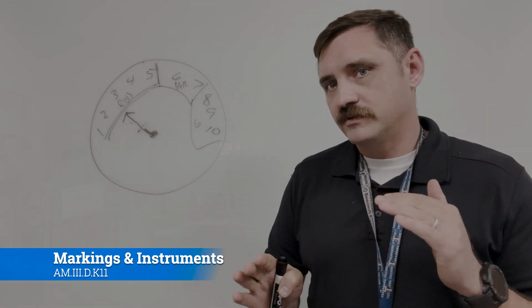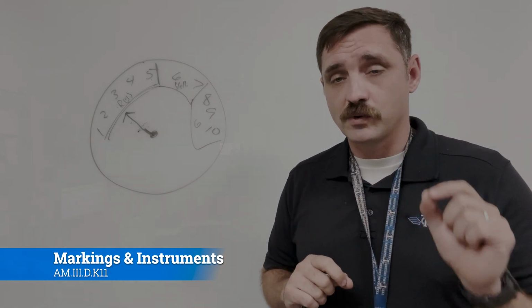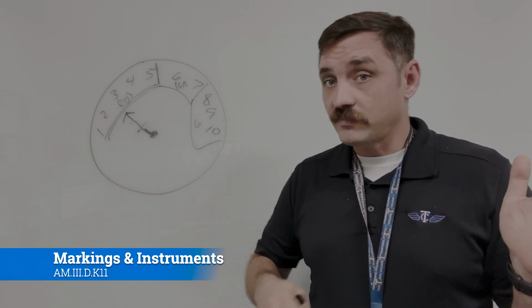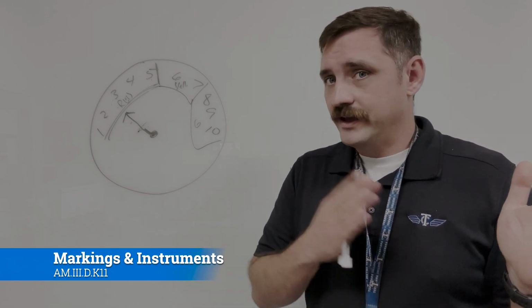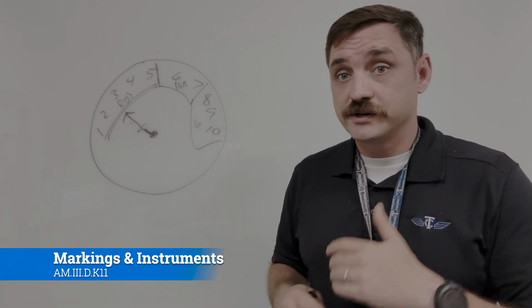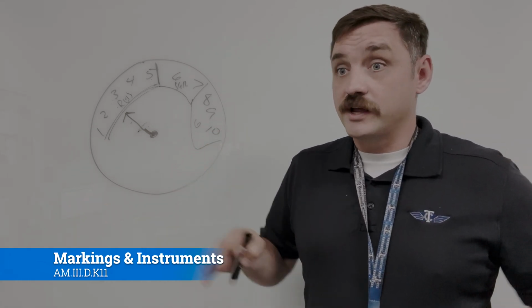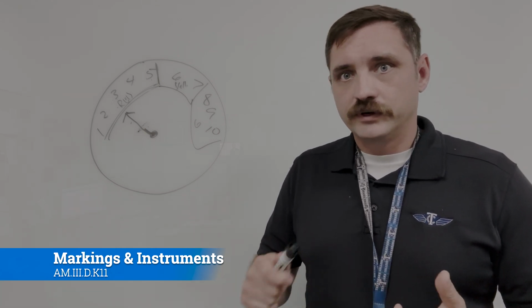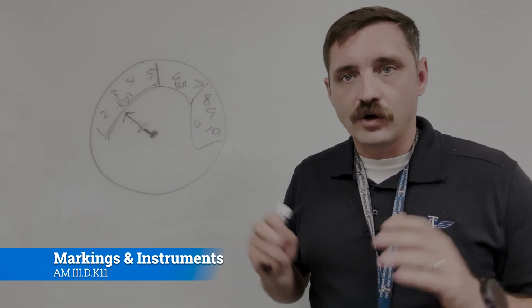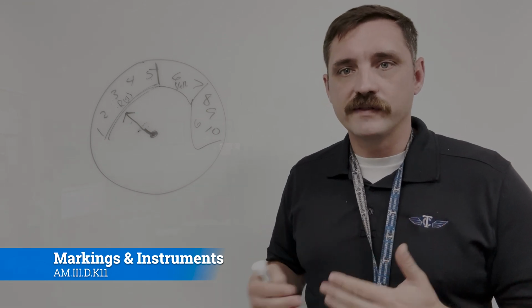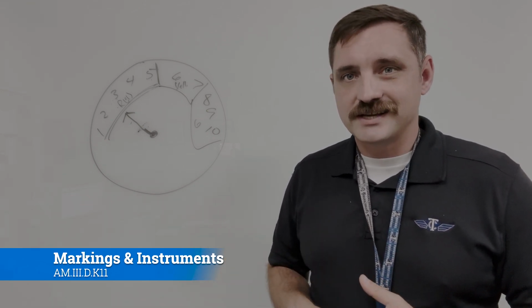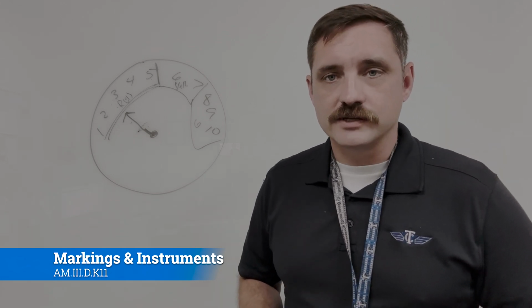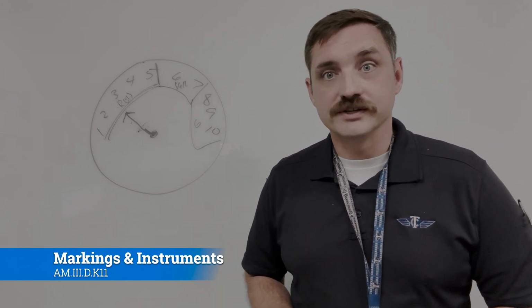And so you always have to think that if you're just going off of a squawk from the pilot saying, hey look, I read this in the cockpit, you want to duplicate it. If you can't duplicate it, it could be wrong. It could be a configuration issue. It could be switchology. It could be it was just a fluke for whatever reason. It could be some sort of contamination of fluid, oil, whatever. There's all these different things, but you want to be really thorough in the way that you're troubleshooting it, so that way you minimize downtime and maximize safety at all points. With that, let's talk about engine runs in the next video.